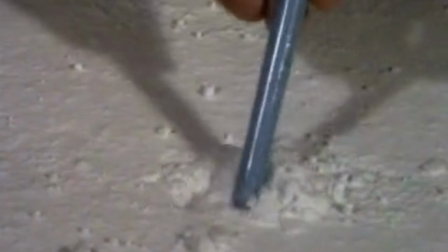It's a good idea to fluff all these tanks every day because the powder will begin to pack in tight from the constant rig vibrations. If it gets too packed, it could pack hard and make it a problem to transfer.